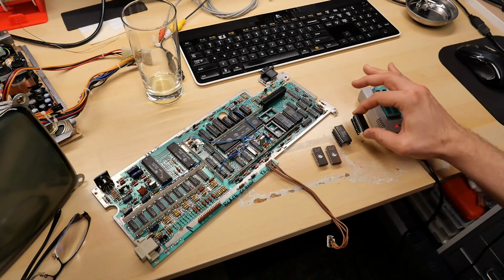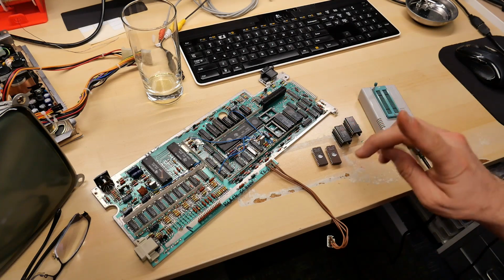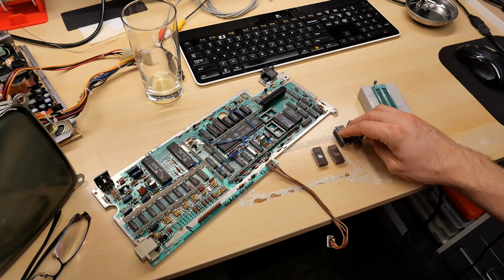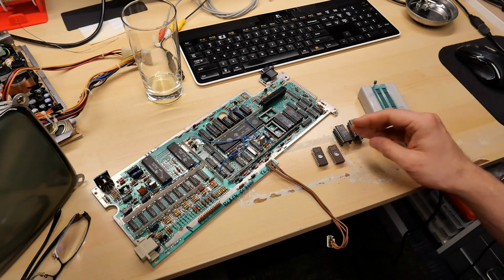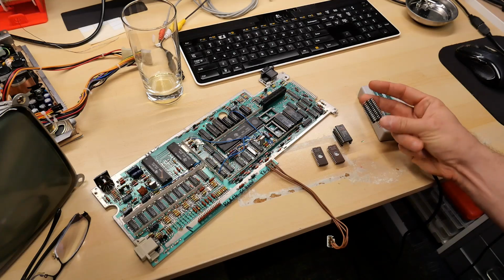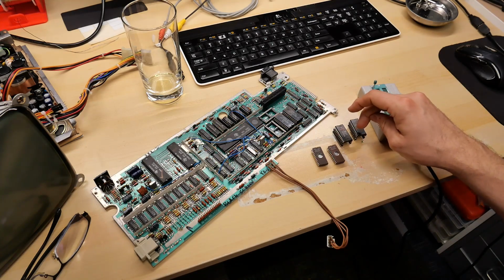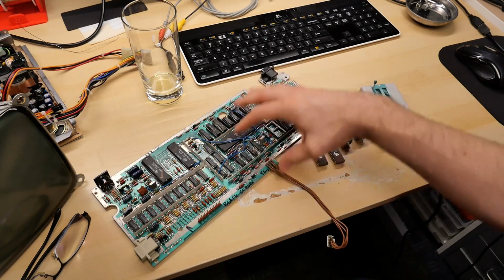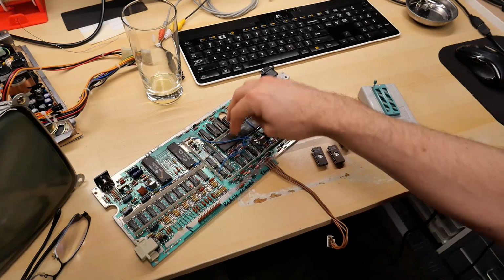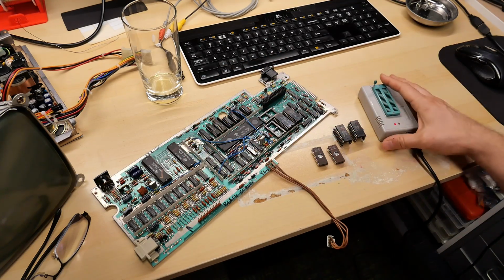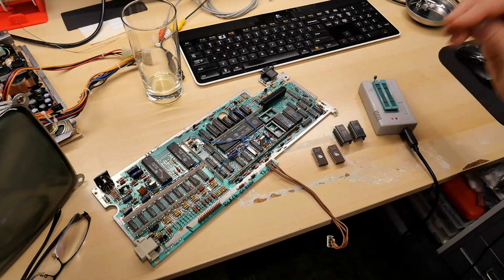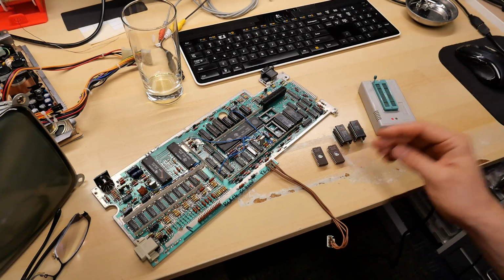And when I tried to read out 2532s, it didn't work. So really this just tells us 100% that these EEPROMs are working, at least they're reading properly from a content perspective. There could still theoretically be an issue on the output transistors on the bus lines, and when it tries to drive the bus, maybe there's not enough strength on those transistors to, say, drive the CPU and everything else on the bus, but it works on the EEPROM programmer. That is a possibility, but at least I know if they read properly, they are not totally dead.